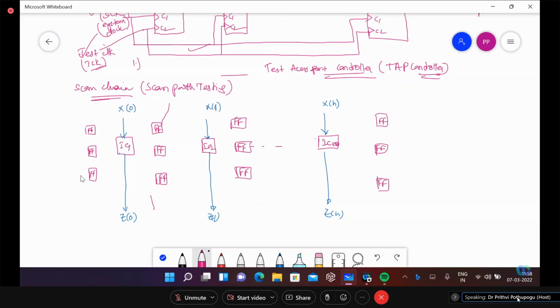If these registers are connected one to one in each stage independently, they form the shift register for that segment alone. Now, one input has to be provided to the system, that is the scan data input. We need to take the scan data out after giving sufficient time for the data to pass through all the flip-flops.